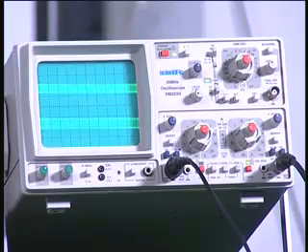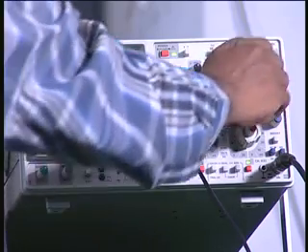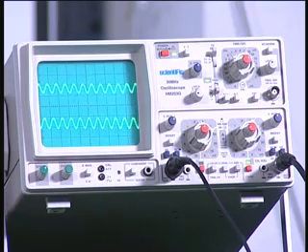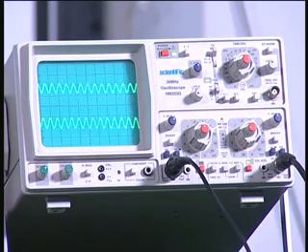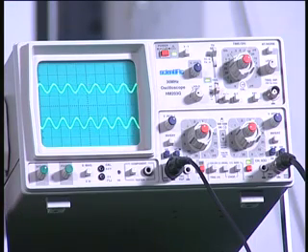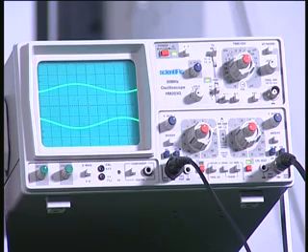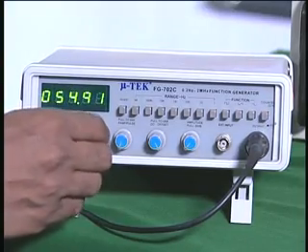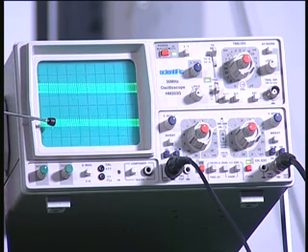See, when I go through the entire range there is no significant change in the amplitudes of both. I will again change the sweep to see a few waves, and I am going up to the extreme end of the knob. You find there is not much of a change in the amplitude. Now I will quickly come back and increase the frequency multiplier to the 100k range. Now I am going to increase in the 100k range. Now you would find as soon as I do that the gain starts decreasing. Now you can see that the gain here has started decreasing.